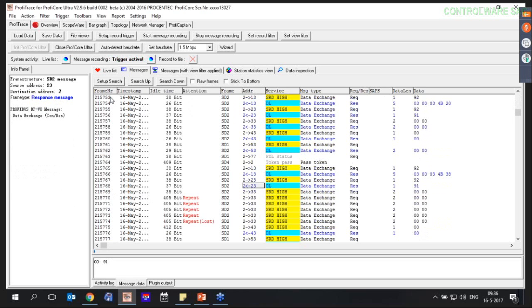So I see that my master number 2 sent the message to number 33, but 33 was not able to send me an answer, so the master will try again, try again, try again, try again, try again. Then he gives up and goes on with the next device. One moment. Yes.